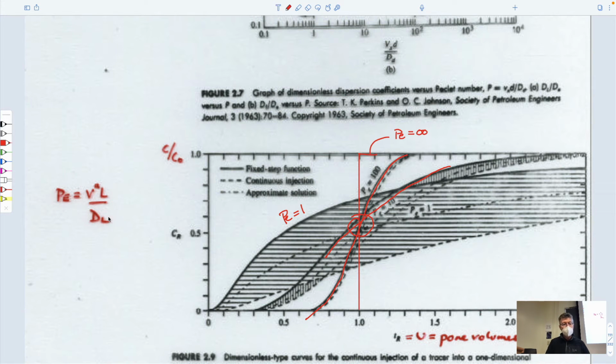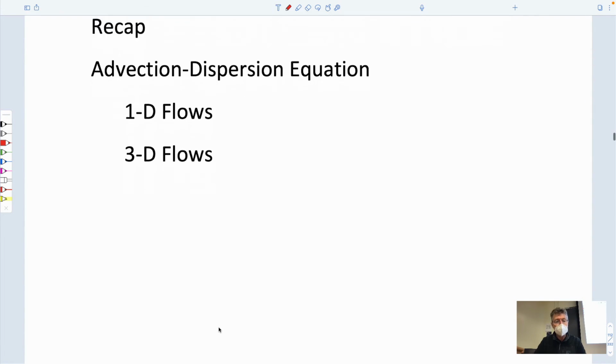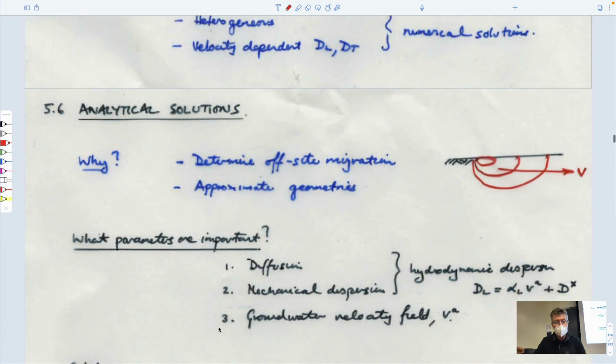If you calculate your Peclet number, which is smaller than 1, then it just means you have to use some assumption that doesn't include this plug flow moving through, where this immediately gives you the location of the front according to this 1 pore volume. That's all it says. So that's an important concept to think about. And I think it's reasonably explained in the videos from 3.1 and 3.2. But that's the punchline, I would say, from what came out of that class.